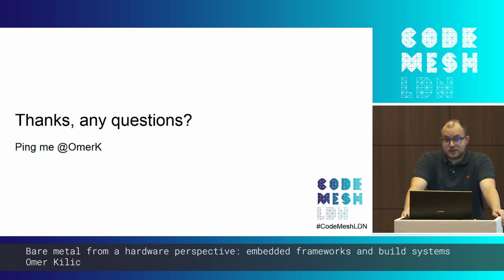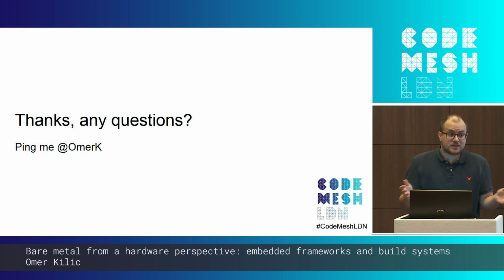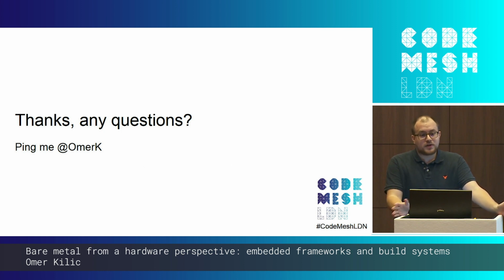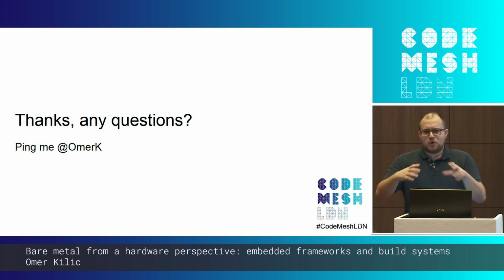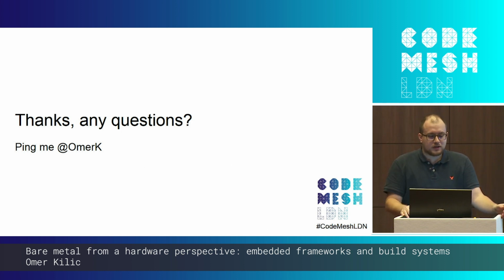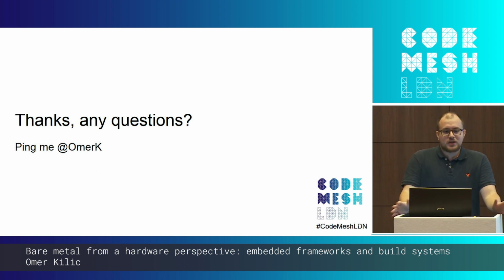So really high quality debugging tools have been around for a very long time. What you're talking about is effectively a tracer, not a debugger. There are companies that do not publish their prices on their websites, selling tracers for a very long time now. So there's Lauterbach, which will sell you a little pod that will debug 100 cores for a lot of money. Unfortunately, that's a very painful world to be in, especially when you get to multi-core and when you're running things like Linux and debugging those kind of embedded devices. I don't have a very good answer for you, unfortunately.